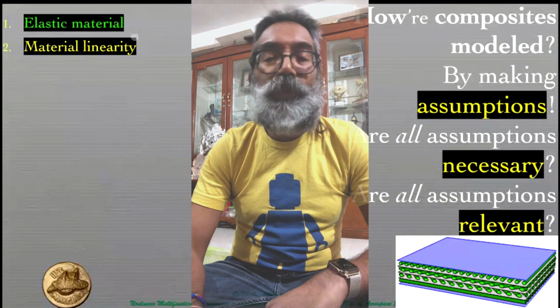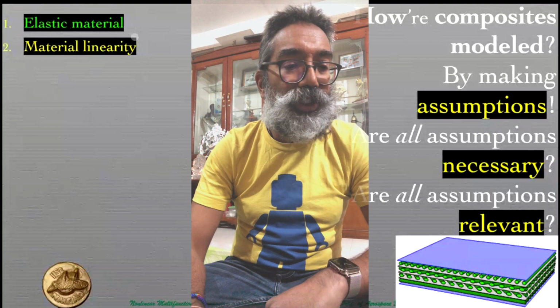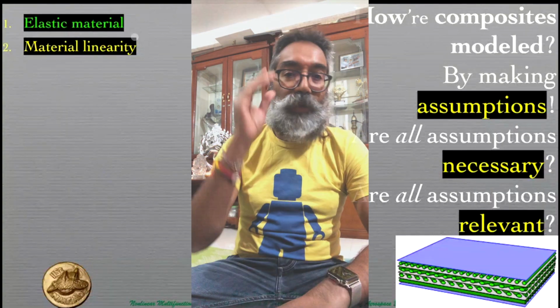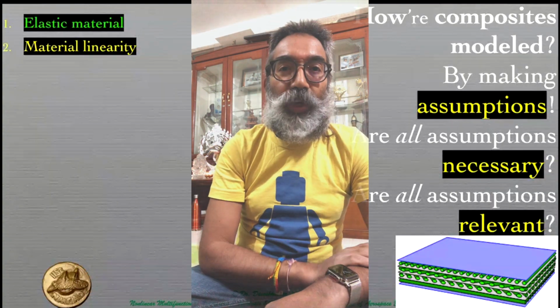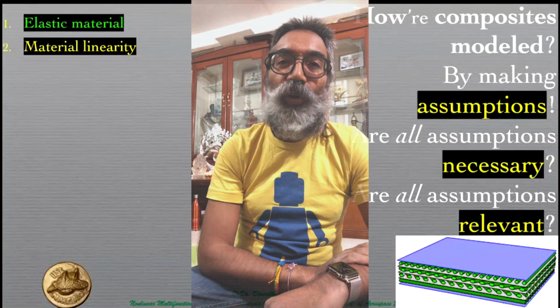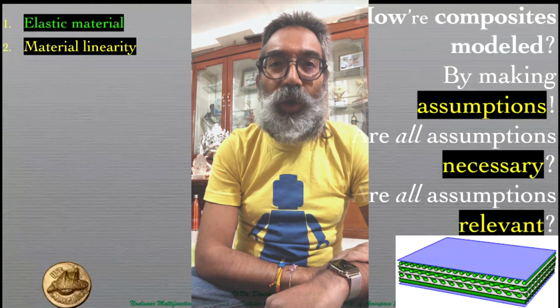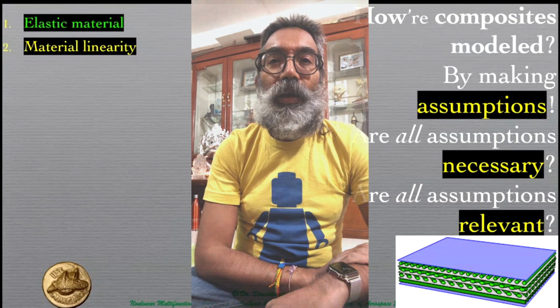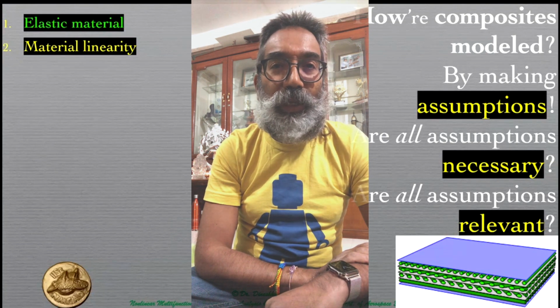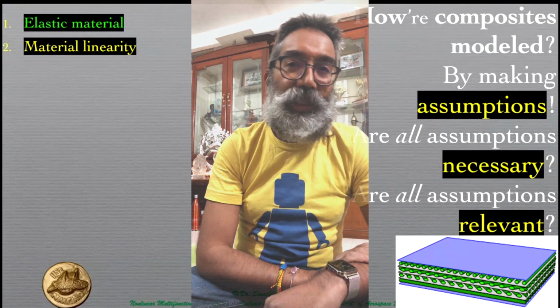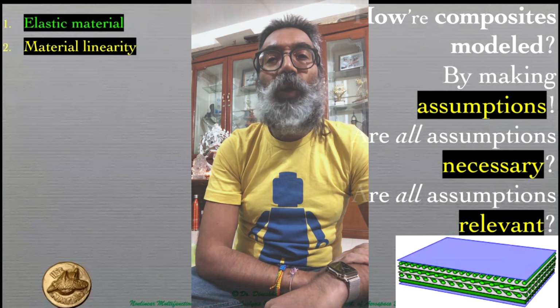But for most part, we are going to consider polymer matrix composites. When we are considering polymer matrix composites, we are talking of a brittle nature, and therefore it would not have anything beyond the elastic limit. It would fail before it gets into anything like that, into a plastic regime, etc. So that's what we are focusing on.